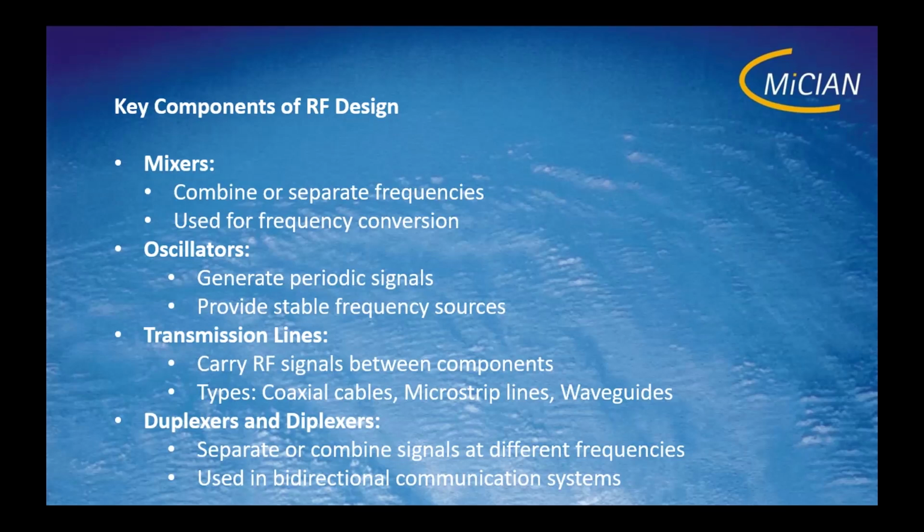Especially when we talk about microstrip lines and waveguides, if you handle a low power circuit, you can construct your design with microstrip lines. But when you need a very big system like in satellites and so on, you need to handle high power. So for that, you will need a thicker transmission medium like waveguides, with thicker metals. So we are using waveguides in the industry.